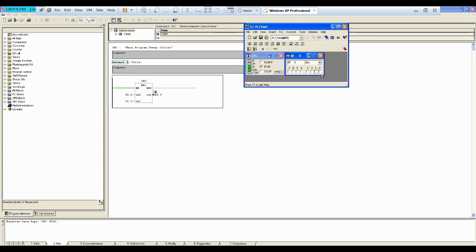If we have in1, it's I0.2, in1, you can see it. We got an output, right? Because for our operation, if any one of that input is high, we will get an output. Let's give it I0.3 here. So if I press I0.3 or I0.2, it is going to turn on. I0.2 here is in1, and I0.3 here is in2.